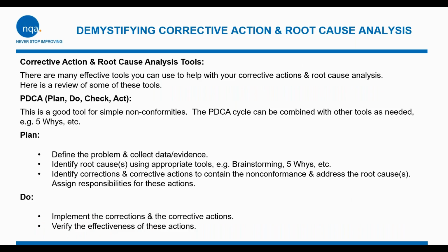Corrective action and root cause analysis tools, here's some examples. So PDCA, I've already mentioned, you can use it for root cause analysis. It's a very simplistic tool and it can be paired with other tools such as 5Y, which we'll come to in a bit. So following the PDCA cycle, plan: define your problem, collect your data and your evidence. Identify root cause through appropriate tools, brainstorming, 5Ys. Identify corrections to address the symptoms and corrective actions to contain the non-conformance and address the root cause. Assign responsibility for delivering on these actions.